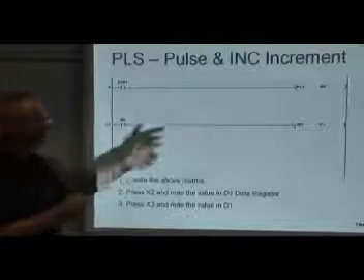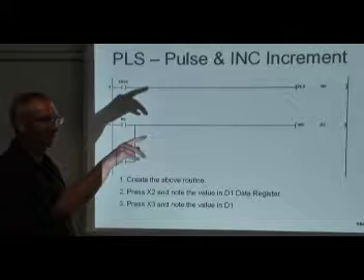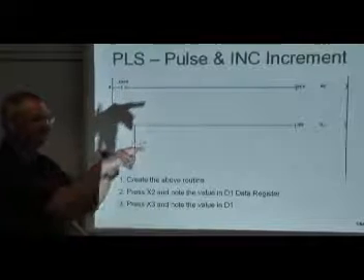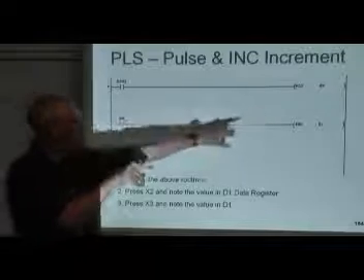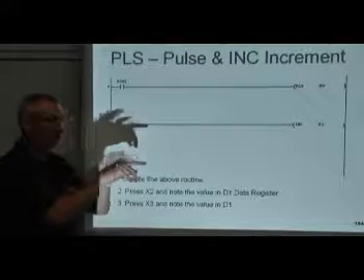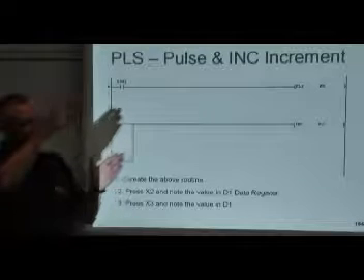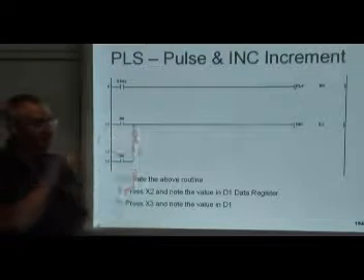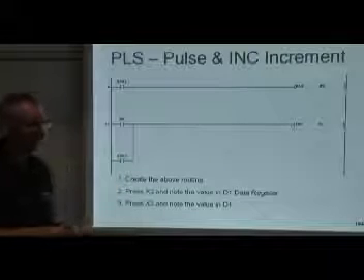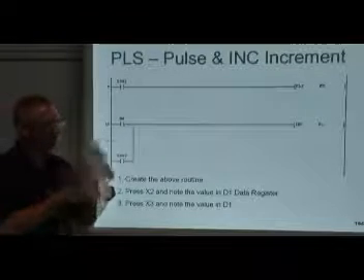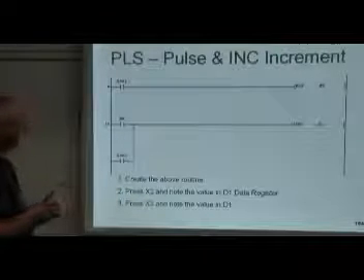So what we do is we use these techniques inside of it, so that if he holds his finger on the speed up button for several seconds, we detect that, and then we activate this to work on the scan, and the speed then starts to ramp up. And when it gets close towards that speed, he lets go, and then he fine-tunes it in until he gets to the speed that he wants. So we can use little tricks like this using the PLC scan to work in our favour.